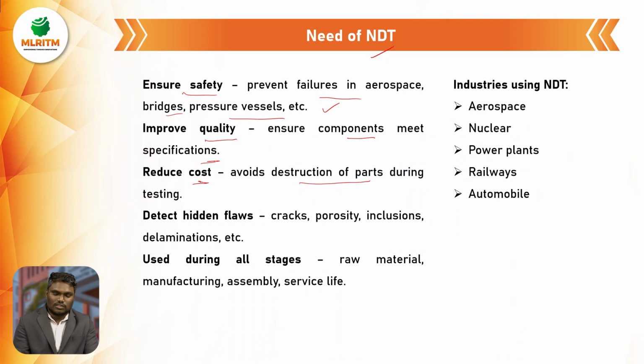So we will reduce the cost right there, and here we can detect whatever flaws or defects were hidden in the material before the application itself, so that we can easily extend the long life of a material. And we can easily detect the hidden flaws. What are the hidden flaws? Some cracks, porosity, inclusions and delaminations.